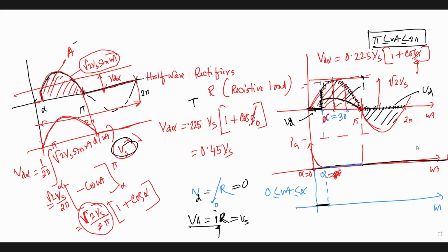You can control it. So how can I control it? Of course, in this book it is given. Inshallah, next class we shall show you how to control it. You must know the input voltage. You have to synchronize it with your electronic circuit by using your op-amp. We call it the control circuit to generate the alpha. We call it the delay angle also, or firing angle or trigger angle. You can make alpha equal to 0. So what is the range of the alpha? 0 to pi.